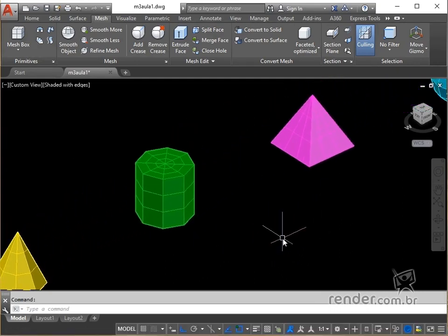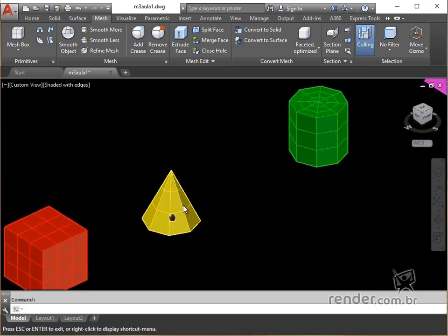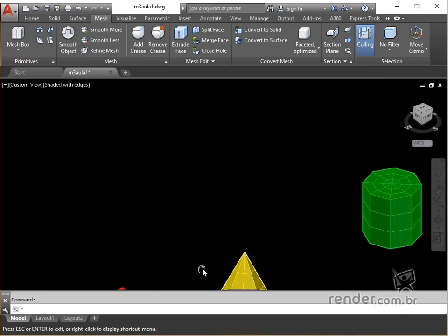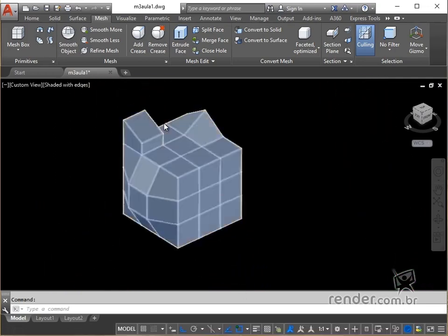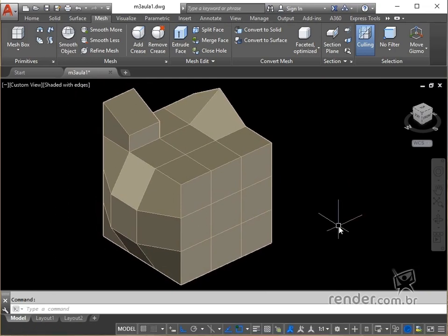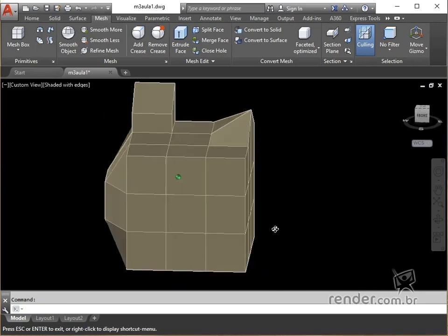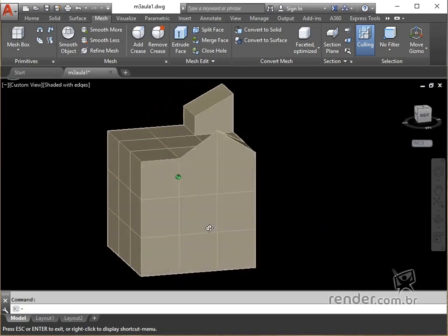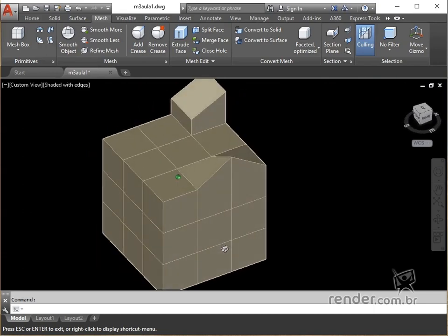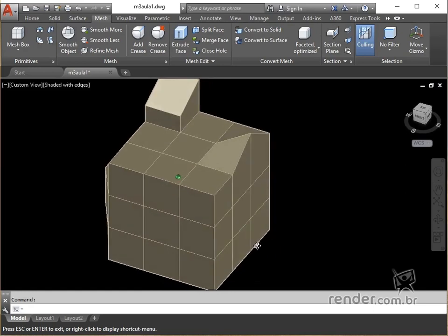This type of modeling uses the freeform concept, where we can divide, extrude, move and rotate the subfaces, creating complex and unique shapes. It is possible to apply several levels of smoothness, bending and splitting. For results with more divisions, we can refine the mesh in specific areas before modifying it. You can drag mesh sub-objects, such as faces, edges, and vertices, to model the mesh object.